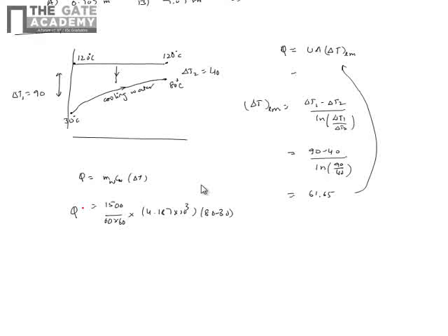So this is the heat transfer. You could get this from either fluid, but for the condensing fluid I don't know the latent heat, so the other way of getting it is from the cooling water. The heat supplied to the cooling water from 30 to 80 is the change in internal energy, which is m c delta T. If I calculate, this value comes out to be 87.22 into 10 power 3 joules per second. So this value I have to equate here.